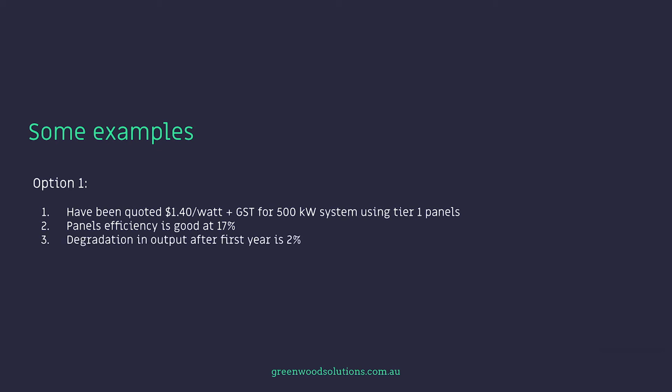Now, the degradation in the output after the first year is 2%, right? Which is a bit of a norm. But after that, 0.7%, up until 25 years. So a bit higher than some of the more premium panels.